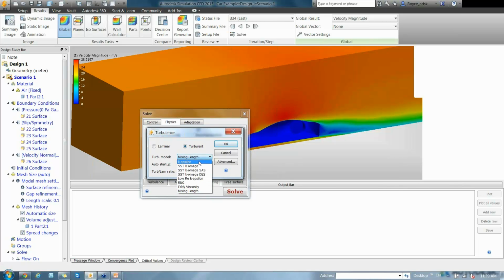For K-epsilon, we default this turb-lam to 100, and that's really done for stability. But sometimes, if a problem is taking a very long time to solve, maybe adjusting that to 10 will actually help speed it up a little bit. Remember, it's adjusted for long term, but it does allow it to maybe start off closer to what it really is. Okay. Hopefully that answered Gary's question.